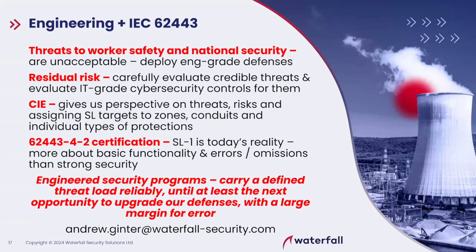And what I'm saying here is that if you use the engineering approach, if you use design basis threat, that gives you guidance as to how to set those levels. And it might be that you don't even need those levels, because if you say my network integrity has to be SL4, really what you're probably saying is it has to be SL4 or better, it has to be engineering grade for the consequence boundary out to the IT network. It doesn't necessarily need to be SL4 to the next layer down of the OT network. And so applying the vector uniformly to everything in the zone might be overkill.